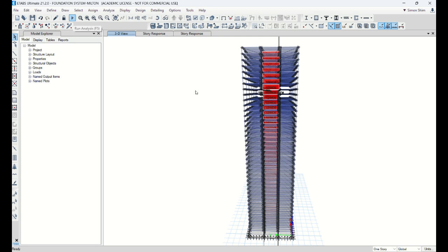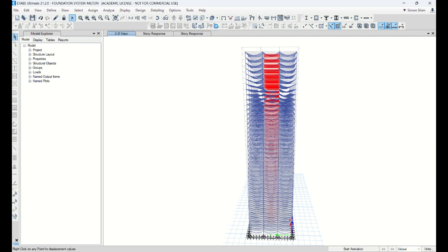Let me show you the total wind story shear and overturning moment. You can summarize it in Excel as well, in a similar way. And so this is, I think, good for now for your lateral system study. But I think what you need is that you need to define the wall thickness and associate it with the concrete strength. So you can just maybe break and categorize maybe in 3 different zones. At this point it is 12 inches, C6 going all the way up, which we haven't done yet.